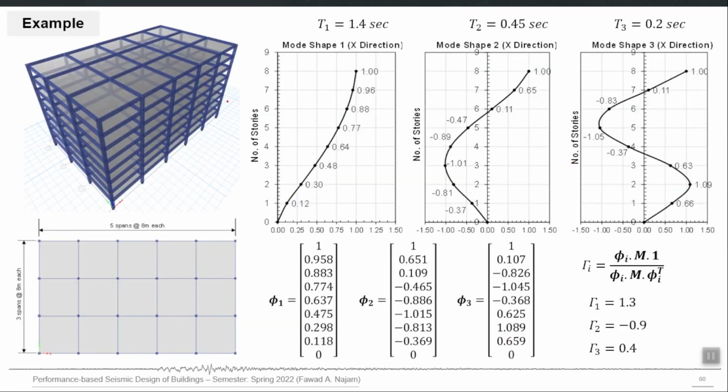So, this is an example here that I have a very regular kind of building, and let us say that I want to apply the response spectrum only in the x direction, separately. Let us assume that it occurs in a seismic design category B such that the orthogonality effects are not required to be accounted. So, when you perform the analysis in x direction, no need to apply forces in y. So, both directions can be assumed uncoupled, separate directions. In that case, let us say that I assume the first three modes contribute significantly to my dynamic response, and from fourth onwards I can ignore.